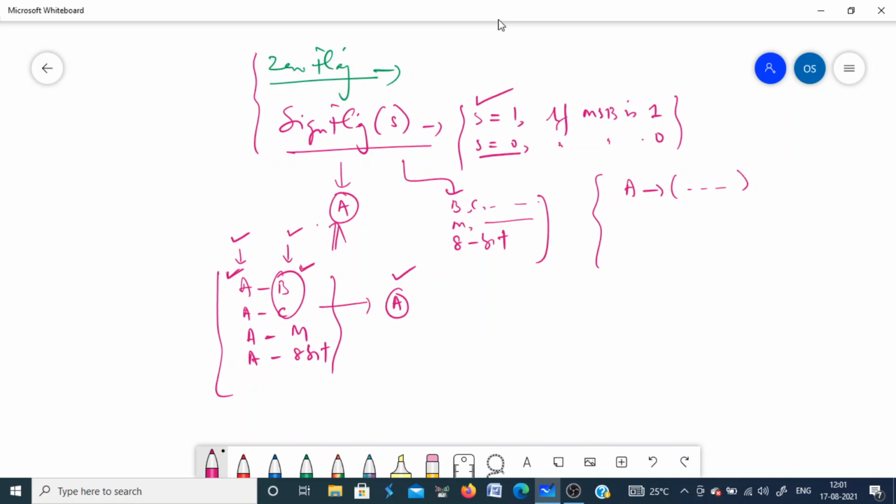And when you write programs, suppose you have a set of data stored in a memory location and you have to write a program to add only the positive values, you have to ignore all the negative numbers. In that case you take the help of the Sign Flag. So every time you subtract the two numbers, you have to check the status of the Sign Flag, whether it is positive or negative. So this is how you use the Sign Flag.